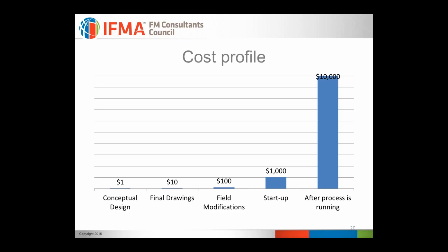And so now you're probably looking at some sort of either an active fall arrest system, or maybe at best case a platform that is elevated up to the motor. Both of those abatement strategies are still less safe than relocating that motor to ground level in the first place. And so not only have you spent more money, you've not even achieved the same level of safety.